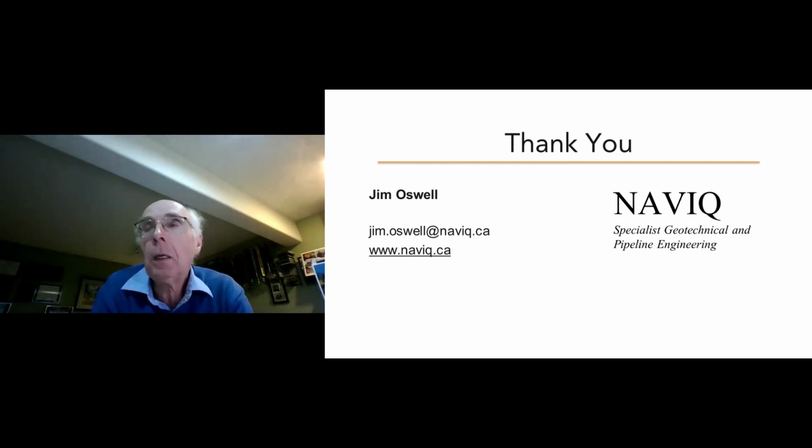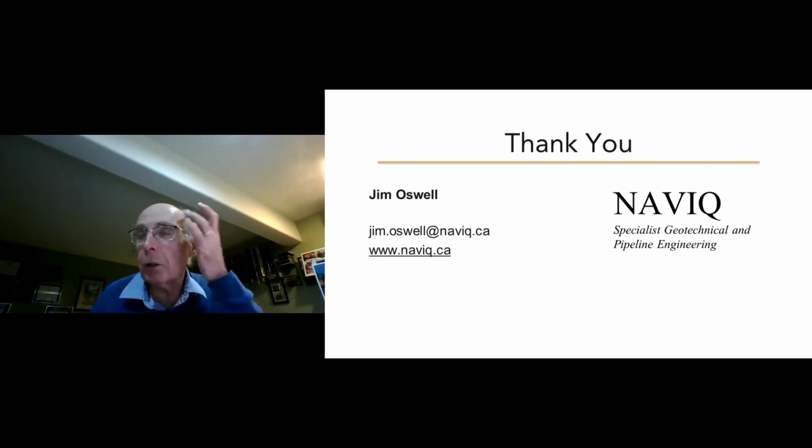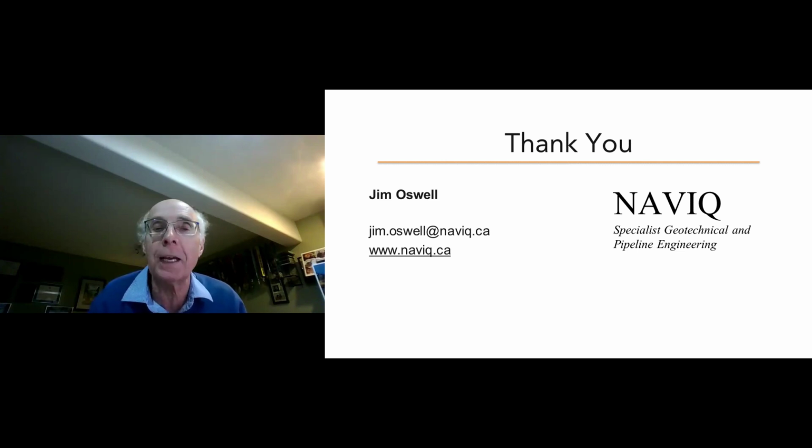Now, strictly speaking, that equation applies to, and I'm going to get into geotech talk here, and I don't know whether the person asking the question is a pipeline engineer or a geotech engineer, but the earth pressure coefficient calculated as 1 minus sine phi is strictly applicable for what's called normally consolidated soils. And one can imagine that a trench backfill, the ditch backfill that is placed around the pipeline, will be normally consolidated, as opposed to this other concept called over-consolidated. And as a result, I think the equation 1 minus sine phi is perfectly applicable to normal backfill that's placed around the pipe. So you can use that equation to calculate your K naught.